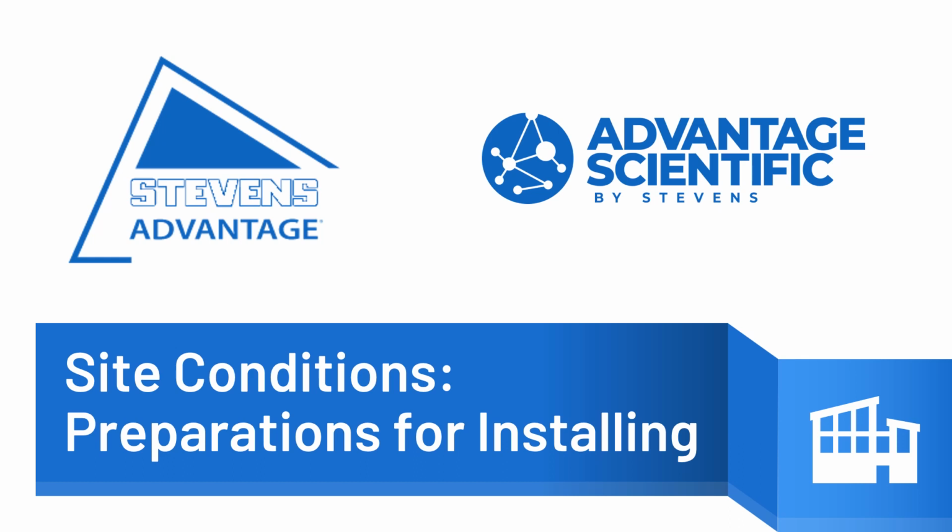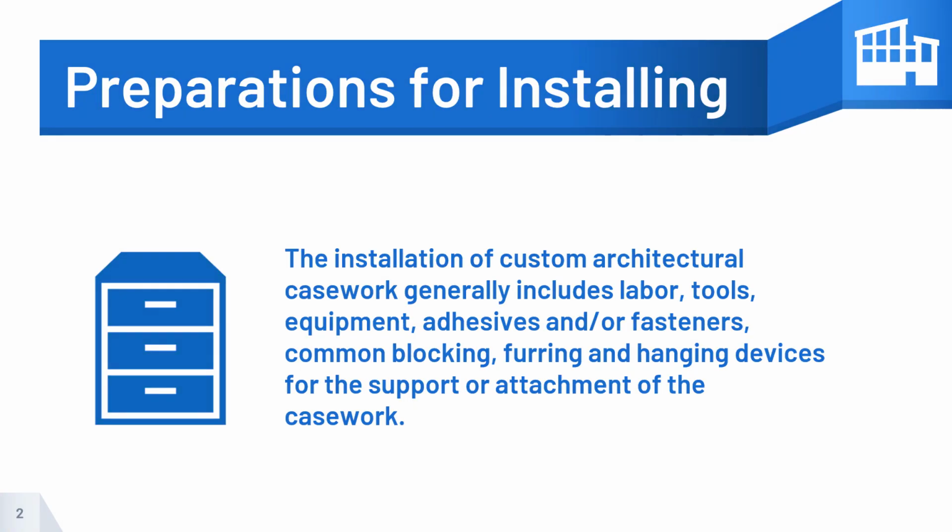Today's topic is site conditions. Preparations for installing architectural casework. The installation of custom architectural casework generally includes labor, tools, equipment, adhesives and/or fasteners, common blocking, furring, and hanging devices for the support or attachment of the casework. Large, detailed tables and in-depth information on proper installation methods are explained in the current AWI Architectural Woodwork Standards.